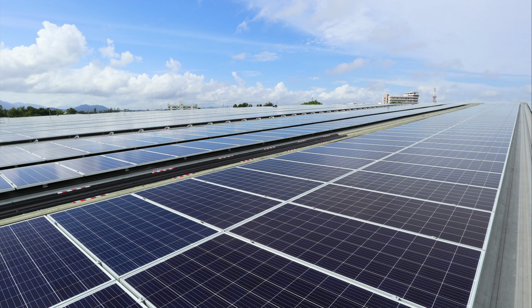For bigger systems, you have to get permission in advance from the DNO. In some cases, it could be necessary for the DNO to upgrade part of their network, which could significantly increase the cost of the project. In the power industry, this application process is known as G99, which is the name of the technical standards that have to be followed.